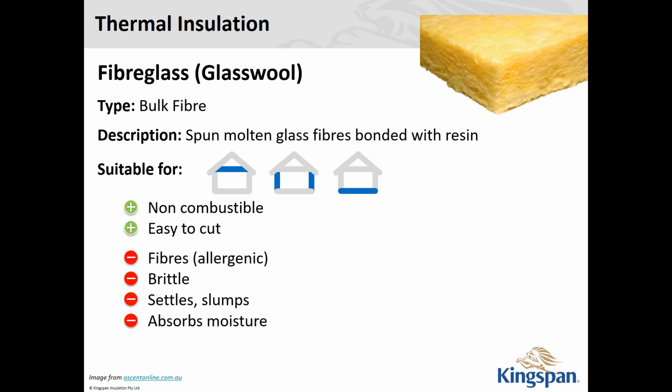Just on that, we actually use our insulated plasterboard quite a fair bit on those types of construction styles. On a raking ceiling, it's our phenolic resin with plasterboard laminated to it, so that material can go up as one panel. The beauty of that is it gives you continuous insulation. Again, it's a good insulator and it's got plasterboard already attached to it. So that gets used quite a fair bit.